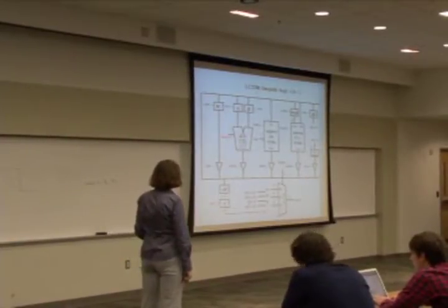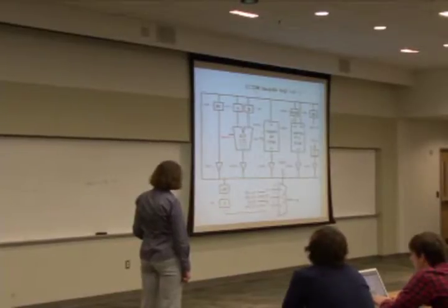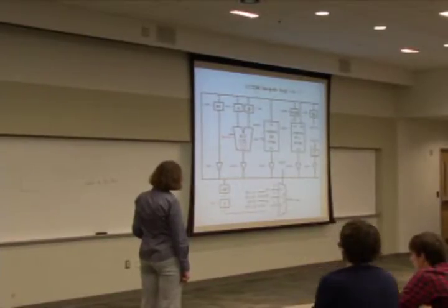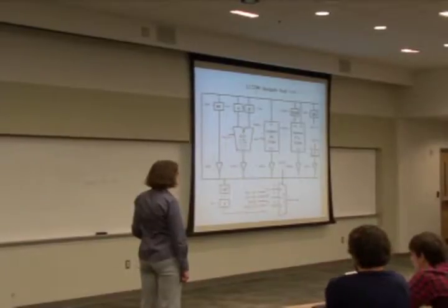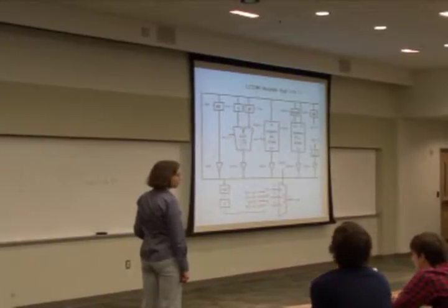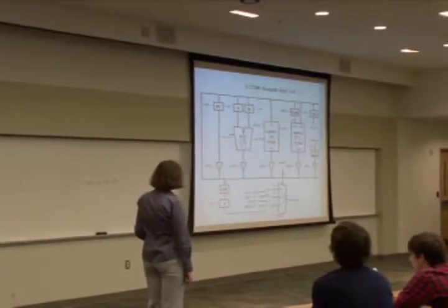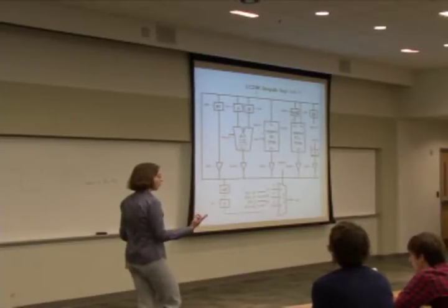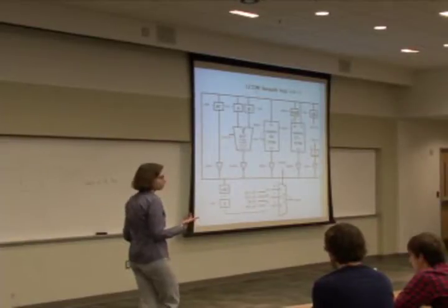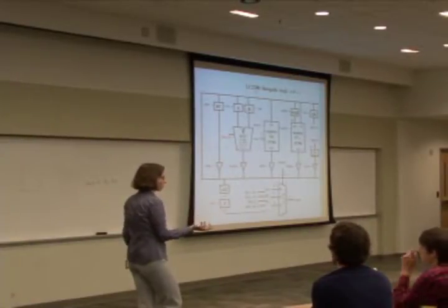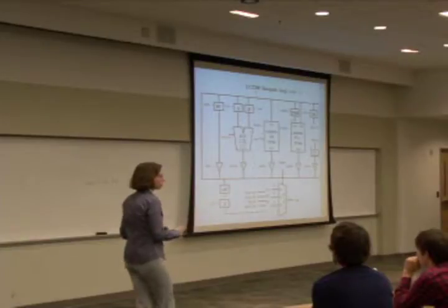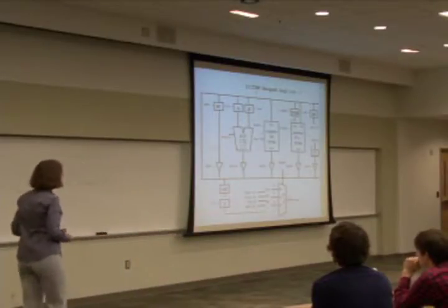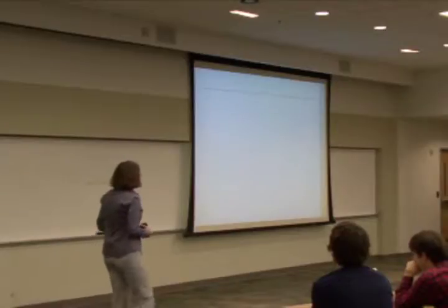And actually, there's an extra step there, because if you look at this, the output of this is 32 bits. And our Z has only 1 bit. So we have a step in between asking, are all bits equal to 0? If it's true, then it's 1. If it's false, then it's 0. So that's why Z has only 1 bit. We don't have to carry all 32 for the result. We just care, is it true or false? So what do we do next?